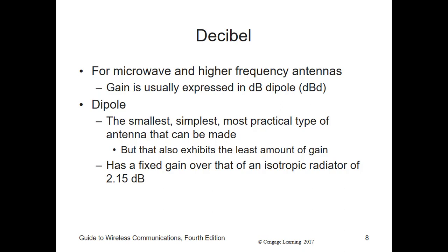Adding another 10 dB multiplies the signal power by 10 again, making it 1,000 milliwatts, or 1 watt. Now we have to take the threes, so adding another 3 dB doubles the signal power, making it 2 watts. Adding another 3 dB doubles the signal power again, making it 4 watts.